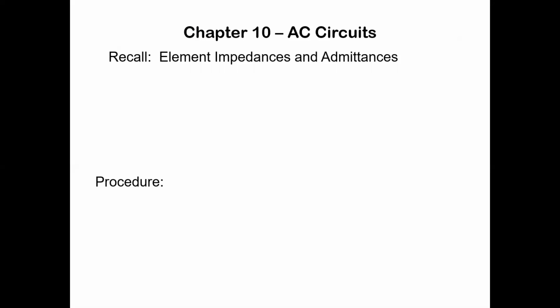So the difference, of course, is we're not looking at resistance anymore. We're going to be looking at impedance, which allows us to include inductors and capacitors as if they are resistors. As a quick summary, the impedance of a resistor is what?